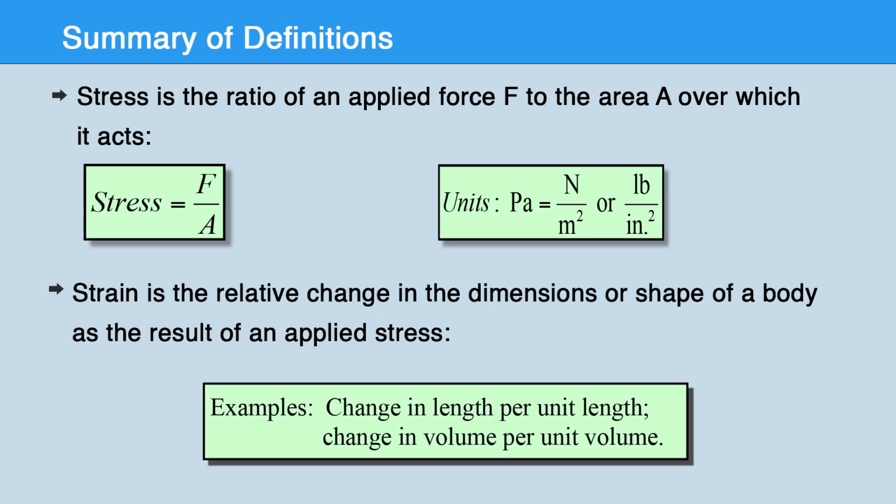Next, our topic is the strain. Strain is the amount of deformation experienced by the body in the direction of the force applied, divided by the initial dimension of the body. The following equation gives the relation for deformation in terms of the length of the solid. Epsilon is equal to delta L by L, where epsilon is the strain due to stress applied, delta L is the change in the length, and L is the original length of the material.